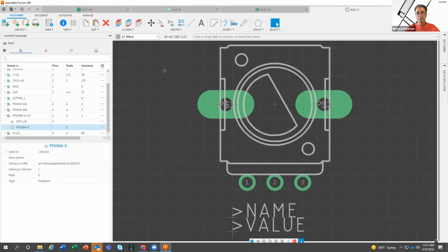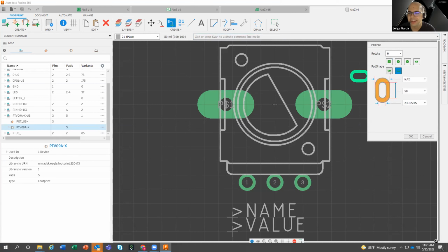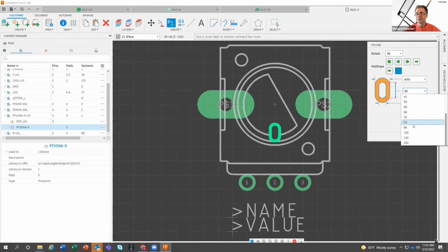You have to draw the milling slot in a layer. You have to use a normal pad. You have to take care of the copper areas in all of the inner layers you use. And now we have the solution for you. It's slotted pads. They're actually here. Yes, we have slotted pads finally. Yeah, that's really nice, it's so easy now. It's just the pad command. You decide the length and width of the slot, and it behaves as a normal pad. Also in the inner layers, it follows the design rules about the annular ring and all the stuff. So it's just a pad now, and that's really nice.